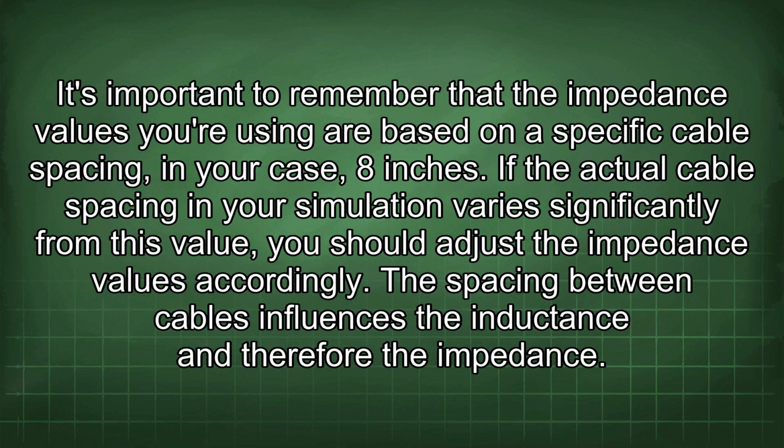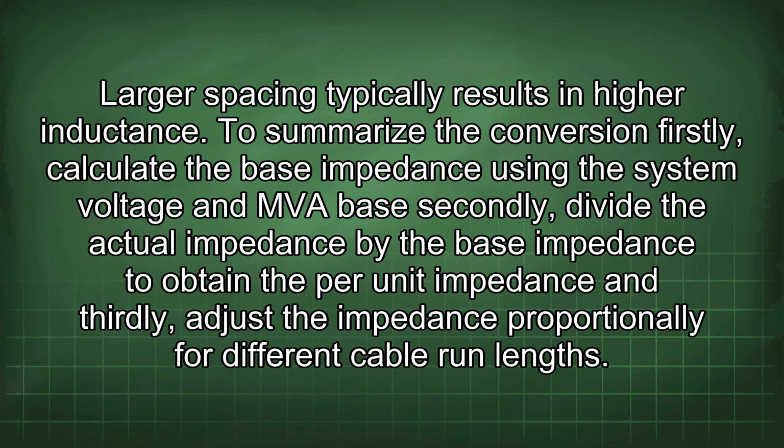It's important to remember that the impedance values you're using are based on a specific cable spacing, in your case, 8 inches. If the actual cable spacing in your simulation varies significantly from this value, you should adjust the impedance values accordingly. The spacing between cables influences the inductance and therefore the impedance. Larger spacing typically results in higher inductance.